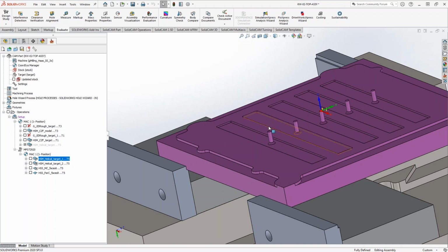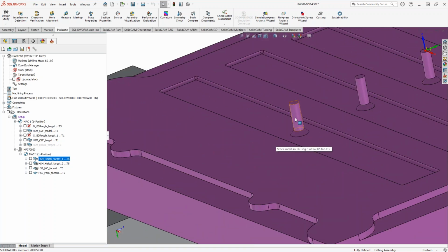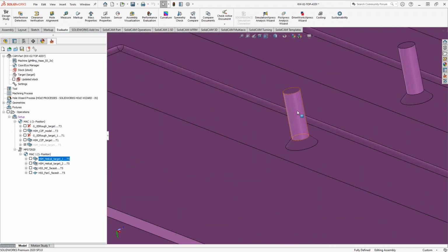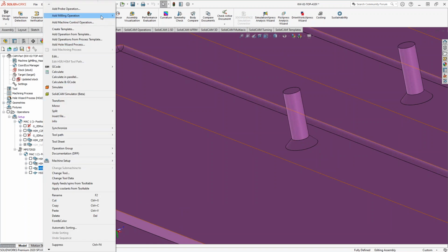So this is one of those things where if we just said, okay, let's just apply an HSM and we're done, then we're getting this sort of thing where, well, we didn't break up the step down, so it's not as good. We have to probably do it again or whatever. Here, if we put in the work of doing the toolpath on this one, toolpath on this one, toolpath on these ones, we get that independent control, and then we're not trying to do one toolpath for the entire thing. We're actually focusing it on this one with the 30 thou step down, this one with 3 thou step over, and then this one probably with a 3 thou step over as well. And let's just take a look at how you could do that with profile.